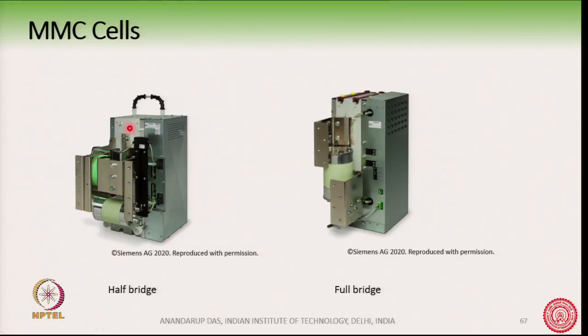So, you can see this is the half bridge configuration. On the right hand side, there is a box here which has these holes. Inside this box are several PCBs, for example, the gate drive board and also the fiber optic board. Okay. Fiber optic board means you have fiber optic signals which are going to the devices. And additional power supplies, and communication boards, communication PCBs, these are all inside this box, and you can see some wires coming out here.